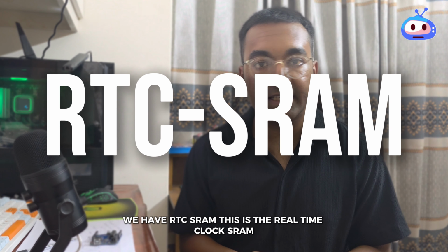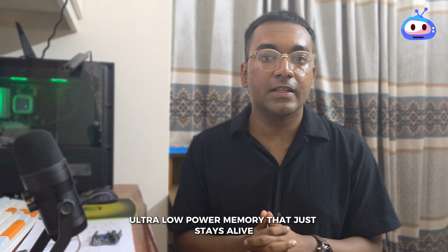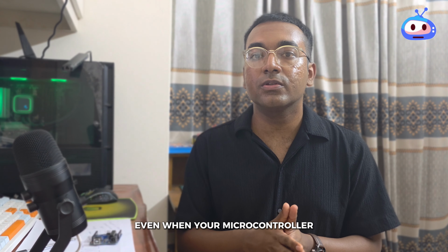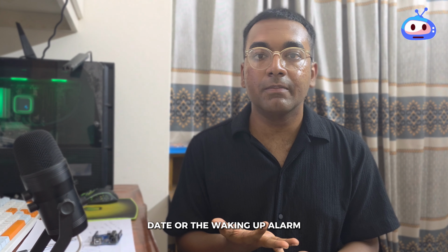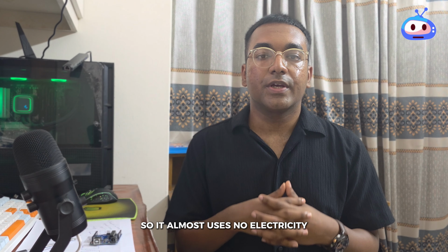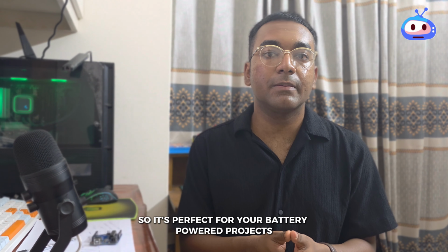Then we have RTC SRAM. This is the real-time clock SRAM. This is a tiny ultra low power memory that stays alive even when your microcontroller goes into deep sleep. It's like a sticky note that remembers the time, date, or the wake-up alarm when the chip is in the deep sleep state. It uses almost no electricity, so it's perfect for your battery powered projects.